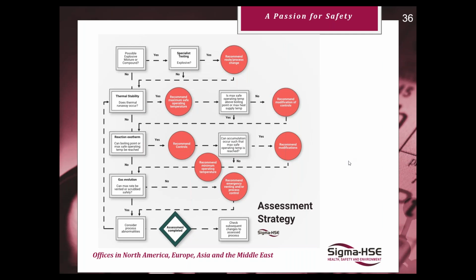So this is a rough assessment strategy. It's taken from a HSE, the UK regulatory body, assessment strategy for performing a chemical process safely. So again, it's just another way of visualizing what we've already been through, starting out early on, maybe by literature or simulation or testing. Is your mixture or compound potentially explosive? Get it tested. If it comes back explosive, then seriously think about potentially changing your route or your process.